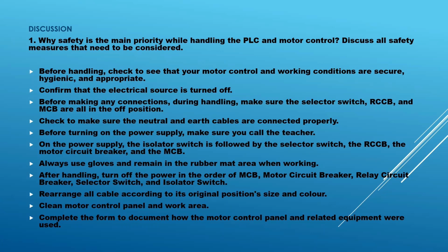After handling, turn off the power in the order of MCB, motor circuit breaker, relay circuit breaker, selector switch, and isolator switch. Then rearrange all cables according to their original position, size, and color. Then clean the motor control panel and work area, and lastly complete the form to record how the motor control panel and related equipment were used.